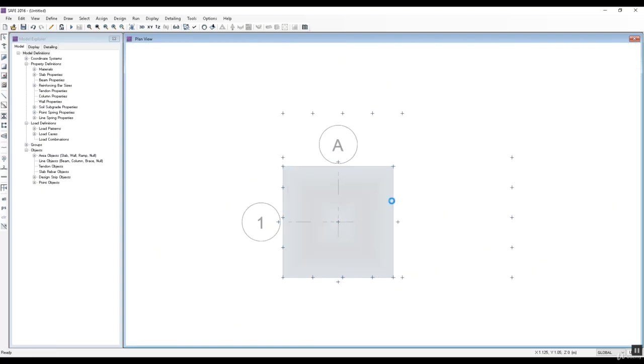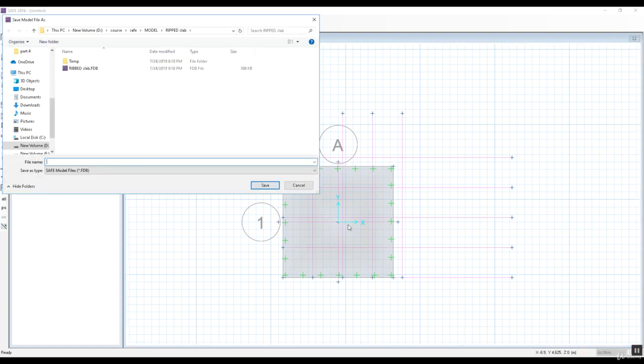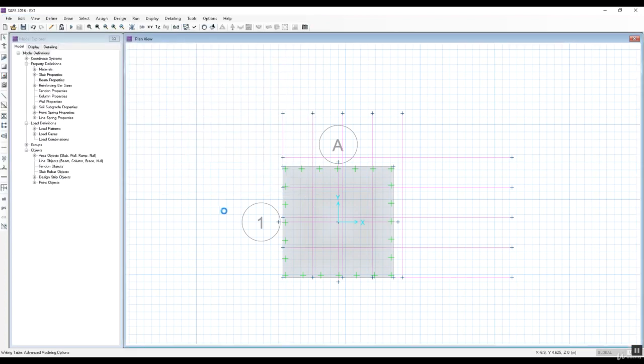Now I have this footing. I added the load. I chose the thickness. I chose the material. I added the soil. I added the strip for the design. Then save. Here, save foundation. Let's name it footing, then example 1, then save.